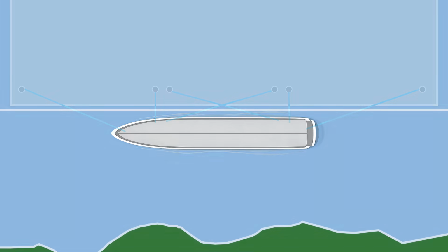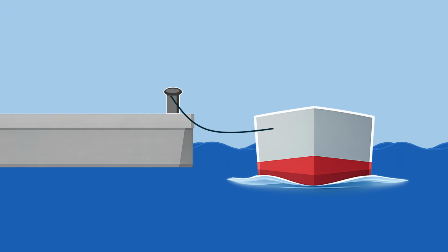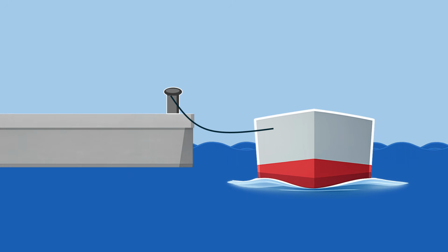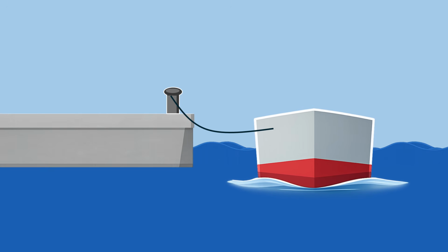their critical role. In exposed locations, engineers often increase system flexibility using longer lines, nylon tails, and softer fender systems. Increased flexibility reduces peak forces and improves the overall behavior of the mooring system under variable environmental conditions.